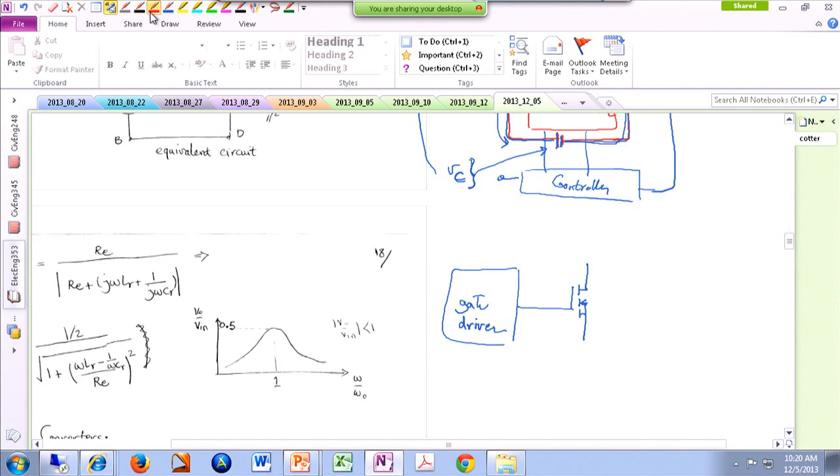And sometimes when you look at the circuit, you see that there is a resistor added here. So the purpose of this resistor is, if you turn the system off, not necessarily the gate driver knows that you're turning everything off. So basically you're disconnecting the power from your gate driver. At the time that you were doing that, if this capacitor was charged, the gate driver just turned off. It doesn't have the opportunity to discharge the cap. So you have turned the system off, but your switch is still on, and that may not be a good thing.